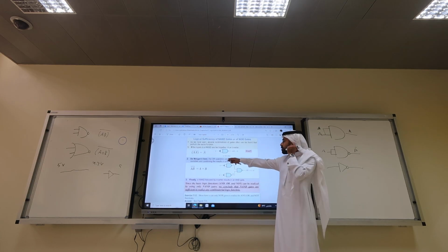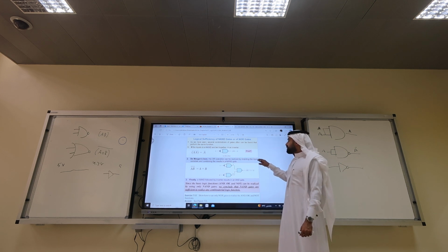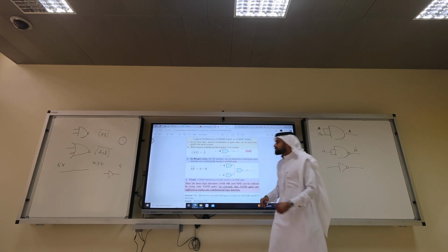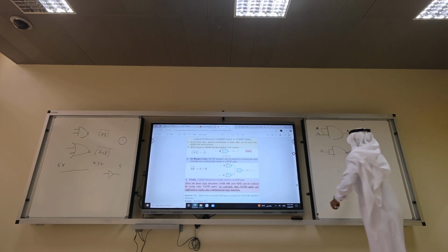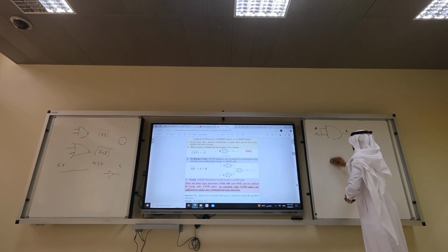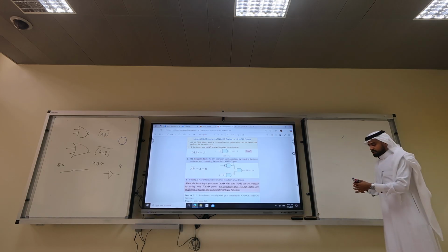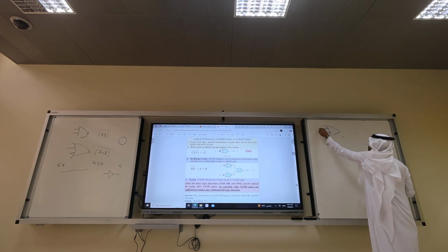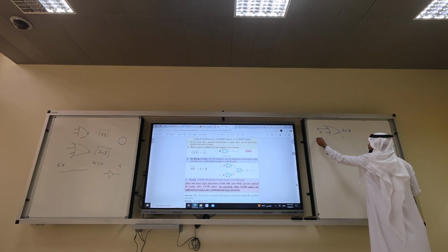By De Morgan's, the OR operation can be realized by inverting the input variables and combining the results in a NAND gate. Let's pretend, again, we don't have lots of ICs. I want to have OR. This is A or B, right? If you apply De Morgan's law, what will happen?